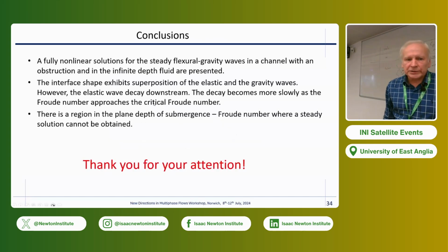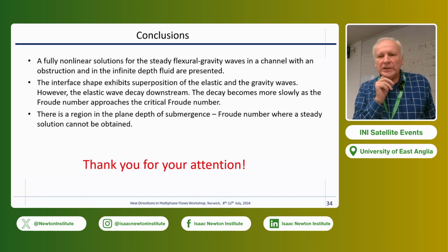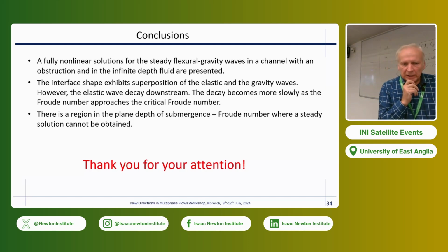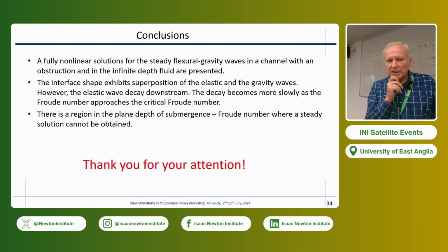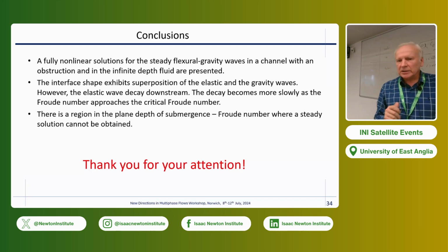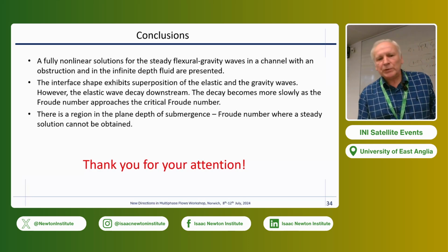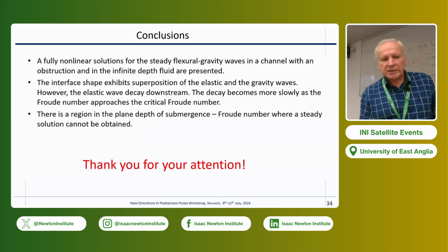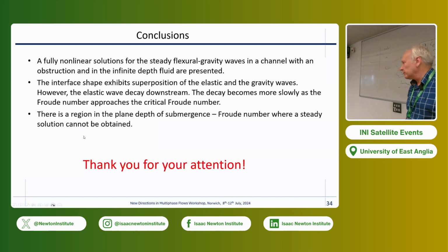So, conclusions. Fully nonlinear solutions of flexural-gravity waves in a channel and in an infinite depth fluid are presented. The interface exhibits a superposition of the elastic and the gravity waves. The elastic waves decay downstream. Decay becomes slower as the Froude number approaches the critical Froude number. And there is a region in the plane of depth of submergence and Froude number where the steady solution cannot be obtained. Thank you for your attention.